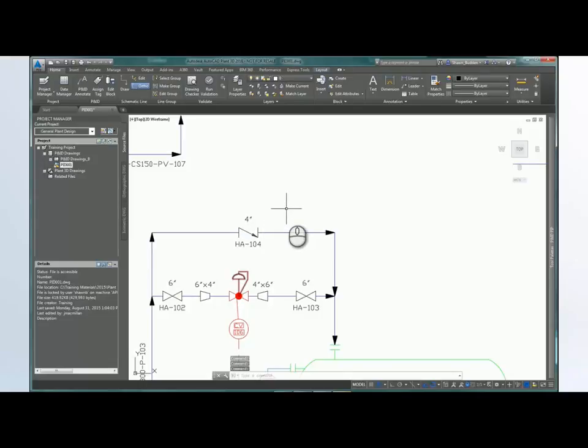You've simply changed that. You also have a flip grip, as you can see the direction that the flow is going on this check valve. If you select it, you see this little arrow right here. There's your flip component, and you can switch your flow. So the grips really make things a lot easier. As we said before, it is AutoCAD, but it is AutoCAD on steroids as well. You have that parametric feature that fits in there.